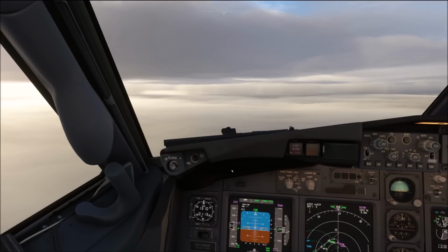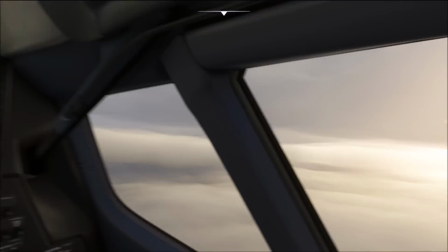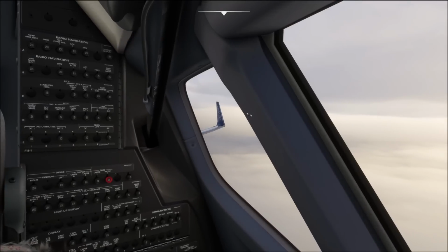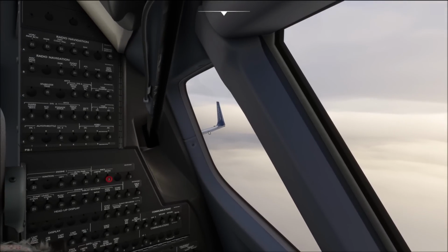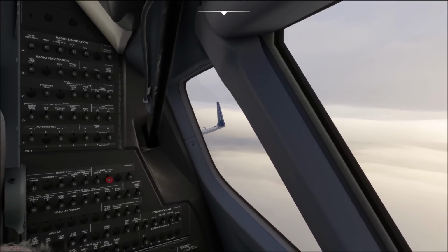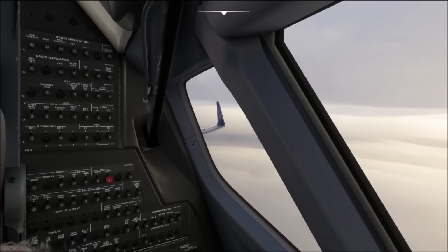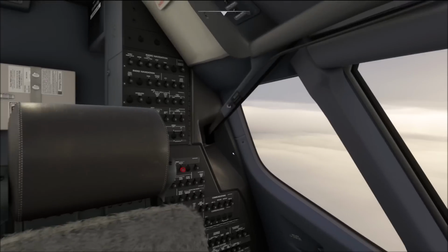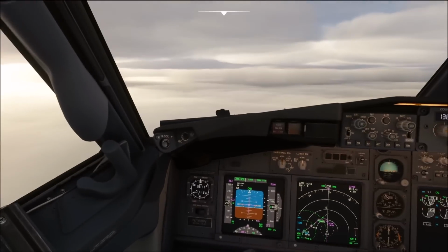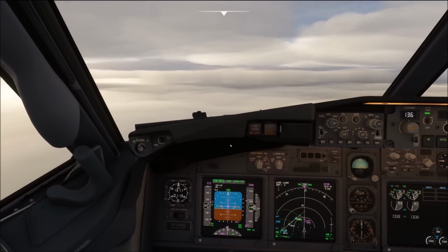If you use wing anti-ice to prevent ice building up on your aircraft, then all that is going to happen is that this ice is going to melt when it hits the leading edge. It flows backwards onto the areas that are not heated, and then it freezes over there, and you have no chance of removing that. So do remember, we use wing anti-ice only to remove ice that has already accumulated on the aircraft.